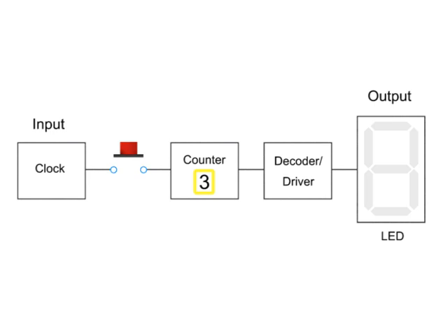Because the counter cycles through digits so quickly, it's impossible to tell where it will stop. With this button push, it has stopped at 3. The binary output from the counter representing the number 3 is translated by the decoder into a 7-segment code, and the LED display driver lights the appropriate segments of the LED display.